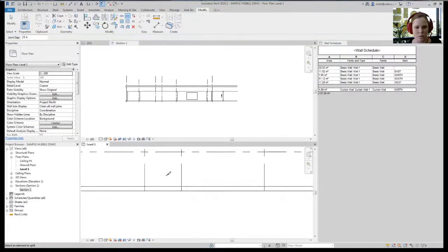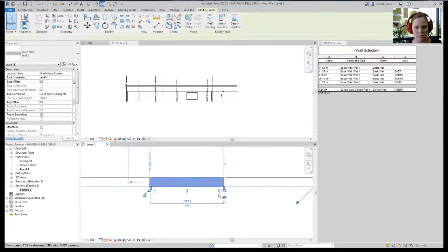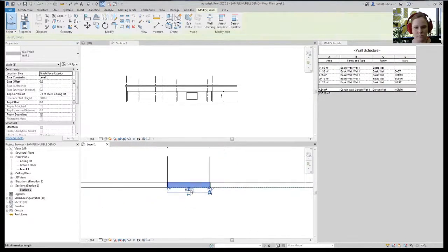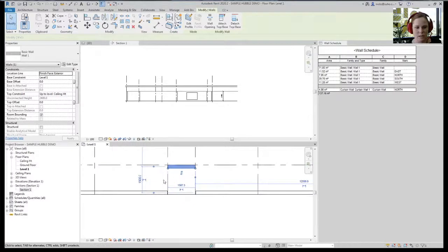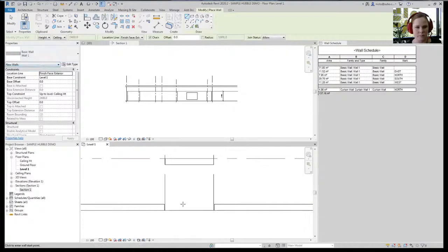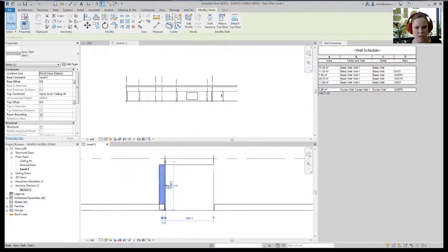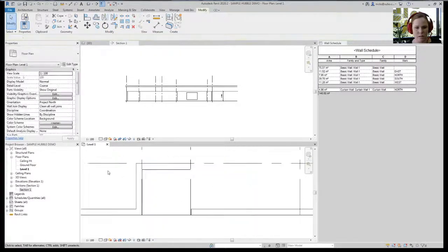So I am going to split this wall. Also got to make sure that those locks are turned off. So select that and then unlock it from all the other planes. You can see another little padlock there that's on. Okay, let's see if this moves without moving everything. Good. Okay, so we're starting to get that courtyard shape now. I'm going to turn that join on so that when I draw the other walls in that it joins together. And for the purpose of this I'm just drawing the exterior face. Now that's not joining because we need to click that little button. Good. And I'm just going to make that nice and even, just to make sure my wall areas are more accurate.